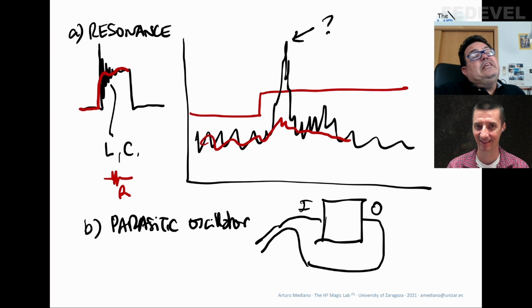It's hard, but you have tools like, for example, near-field probes. With near-field probes, you can go around the circuit and you can identify that the noise is coming from the DC-DC converter. And then you can try to analyze how is the schematic, how is the layout, and you can try to do something in the prototype to confirm if this is the problem or not.